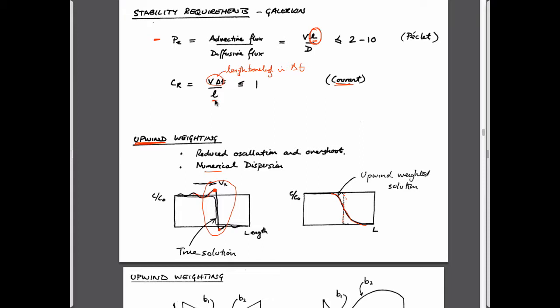For both, yes, both will not work well. Have a problem. So by that time step, I think, yeah. The other thing which I haven't really thought through beforehand: certainly, if you reduce your Peclet number by having smaller elements, then implicitly, I suppose, you increase your Courant number. So you work against yourself. So you have to even further reduce the time step to be able to capture it.